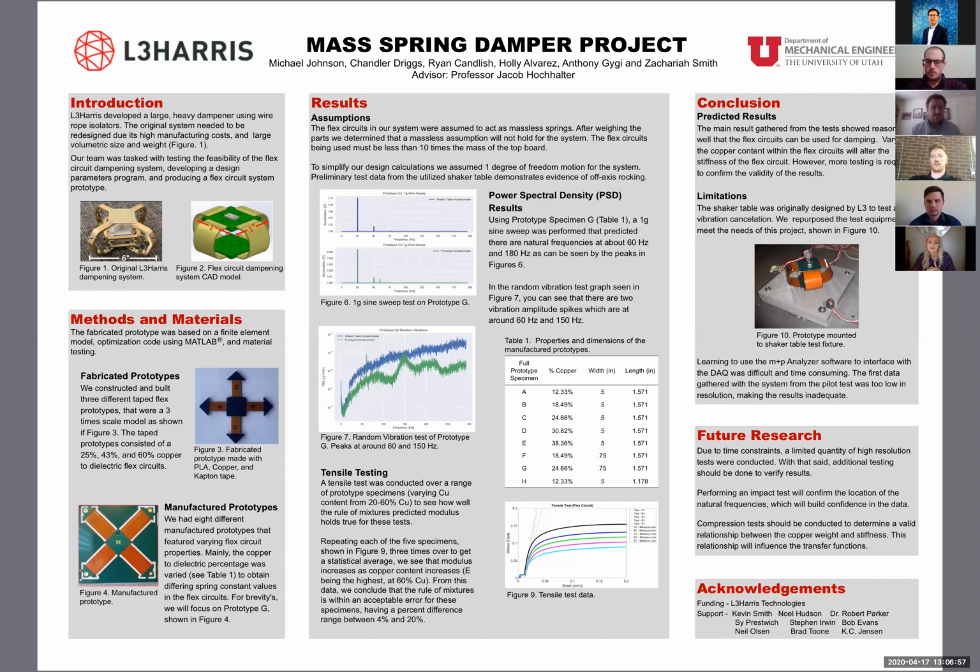It has a 25% copper to dielectric ratio with a width 3/4 of an inch and a length just over 1.5 inches. And the thickness of the flex material is 14 mils. And Zach is going to talk a little bit later about the results of the response data that we found through this test.